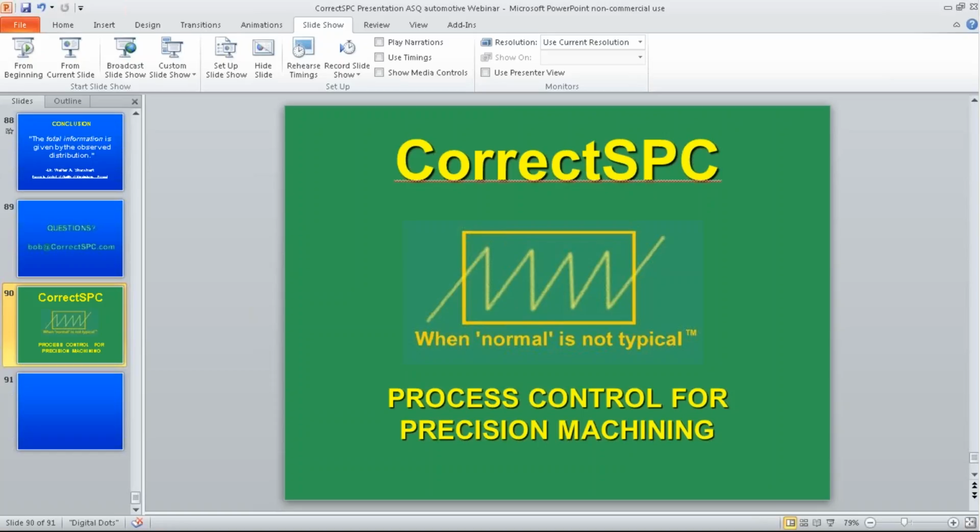Here's a question. Are 3 to 5 measurements across a sample diameter, or even for a sphere, reasonable to determine the max and min diameters? It depends on how much roundness you have. I prefer at least 4. I would do at least 4. I found when doing a CMM that if you do 8 points, which would be close to 4 diameters, you don't get much better than that by doing 10 or 12.